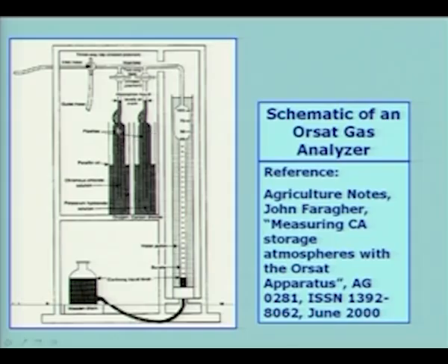And then there are 2 reagent flasks here, and this is communicated to the burette. Now, imagine how it will work. It is very simple. So, this is the lower level or the 0 level, and when there is no sample in the burette, when it is open to the atmosphere, we can bring the level such that it is in this level. So, this bottle can be raised up and down to change the level of the liquid or the separating liquid, in this case water.